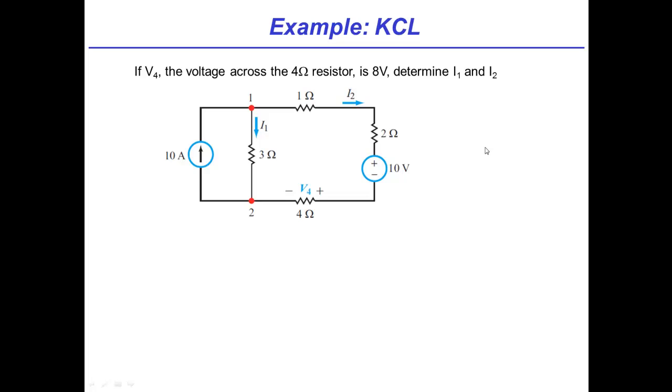And so now, Michelle, maybe you can work through an example. All right, let's try one. So here we've got a circuit. Let's start getting used to just looking at them and finding the pieces of it before we even start. So we notice right away that we've got two sources. We've got a 10 amp current source, and 10 amps positive is defined by this arrow. So I know it's positive 10 amps going up like this down this branch.